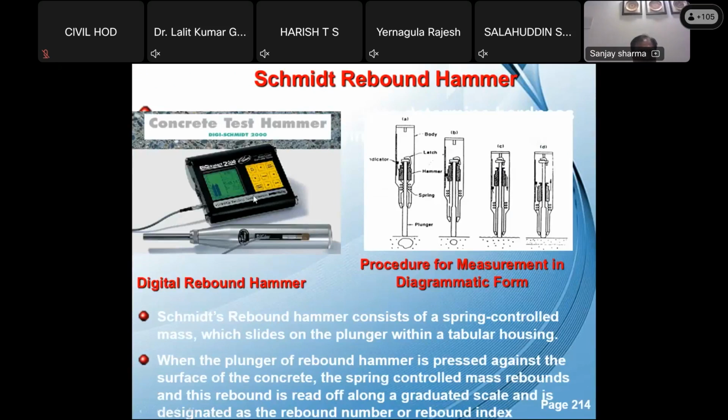But here it is microprocessor based, you can say some sort of intelligent system. In this system you can fix how many values are to be averaged and how many values are to be discarded, like the highest two values and the lowest two values, or an average of 6 or 8 values, that you can feed in, so you can see what data I require for my intelligent prediction.